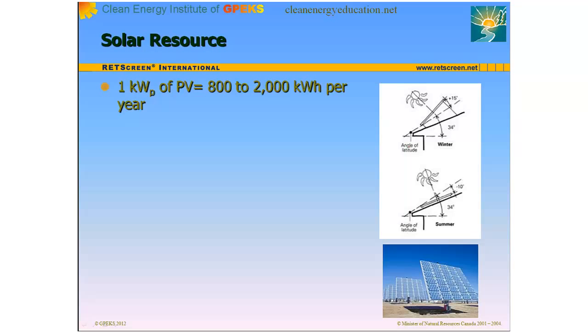Let's examine what this means for photovoltaic systems. First, we need to introduce a bit of terminology. The capacity of a photovoltaic array is rated in terms of its power output under standard test conditions of bright sunshine and cool temperatures. The unit of capacity is the peak watt, which is written as a capital W with a subscript P. A 100 peak watt array, for example, will furnish about 100 watts of power if squarely oriented towards the sun at noon on a cool, clear spring day.